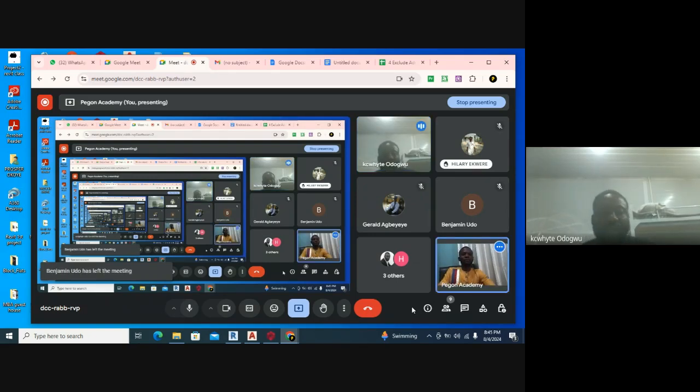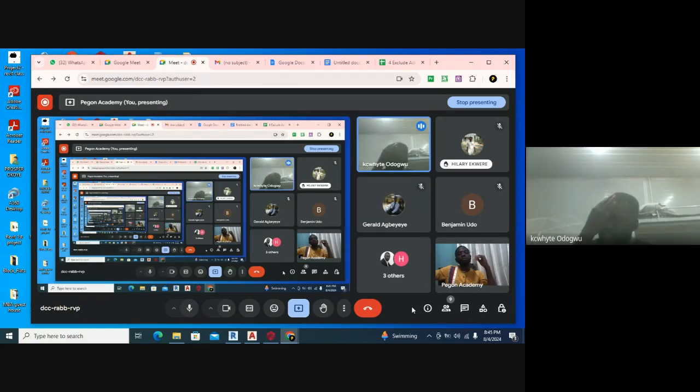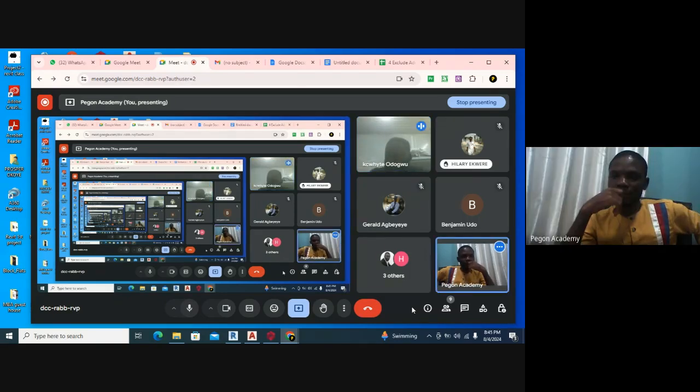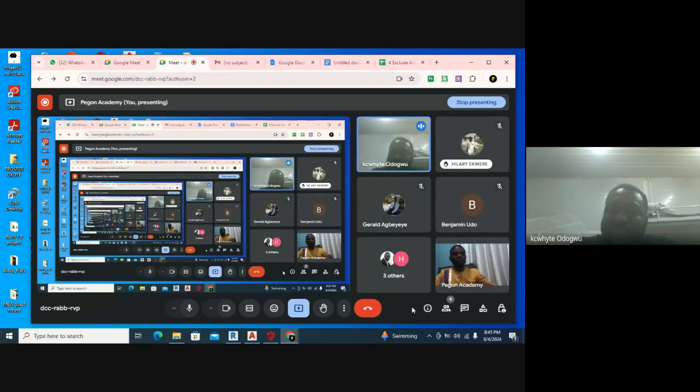So we decided to introduce, like this thing you're talking about, I want to know if this one we are looking at is a kind of strip foundation in a way, because we're combining the pad foundation with a ground beam. Yes, we combine the pad foundation with the ground beam. The ground beam height is just 1 meter.